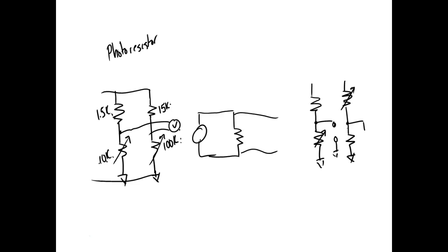So we could adjust it and say, okay, this would be equal to 32, but it would be a little bit harder. So just about any sensor that's going to give us a voltage relative to a resistance, we want to do things with it. We don't want to modify it before it gets to our computer, and we'll put it in a bridge.